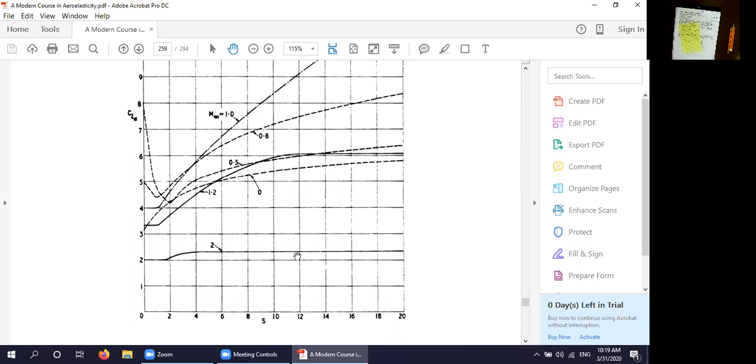But the point is that at Mach 2, the result at short time given by piston theory and the result at large time, which is basically the steady flow result, they're very close, right? There's not much difference, which tells you that at high Mach numbers, piston theory gives you a pretty good answer, although strictly speaking, it's only the right answer at short times. It really is a pretty good approximation for a large time.